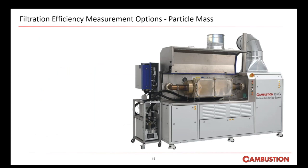Now looking at the same DPG, but an alternative to the particle number counter is the smoke meter. Seen here on the end, this DPG is fitted with an AVL smoke meter. This measures the particle mass by measuring the amount of blackening on a reference white filter paper. This is also used for soot load monitoring. During the load, we measure the live concentration and see if it varies at all. The filtration efficiency data is similar to the PN counter, but slower and less sensitive. It's often sufficient, and the instrument is far more robust and a lot cheaper, actually.